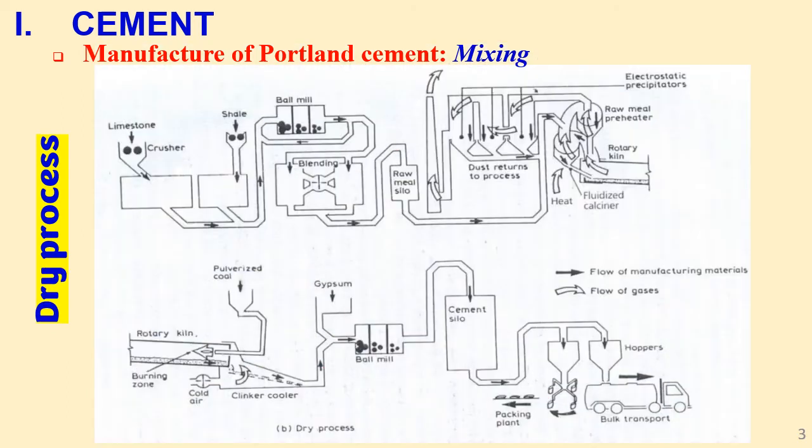But before then, I need to mention the dry process. In the dry process, we use it if the materials cannot disintegrate in water, or we have a shortage of water needed for mixing, or in a very cold country where we don't want to take the risk of using water, which can cause problems if freezing occurs. So in that case, once you grind the limestone in a crusher, and the shale, which is the clay, the mixing is done aided by air.